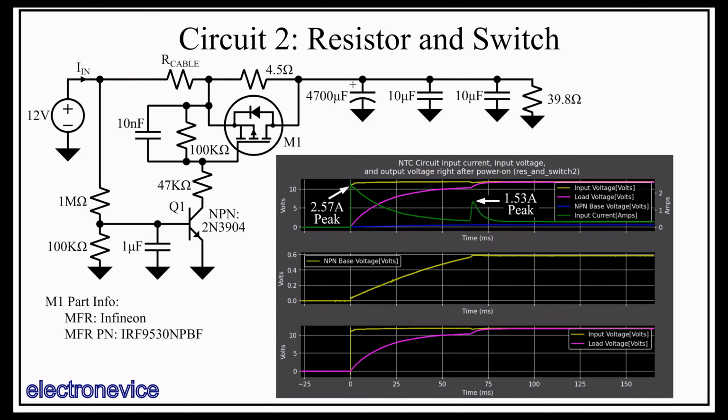However, since thermistor heat-up timescales are on the order of seconds to tens of seconds, you might need a different timing circuit than the one used here, as using this type of timing circuit would require a massive base capacitor to get a 10-second delay before the base turn-on, even with a 10 megaohm resistor. Those caveats aside, though, this circuit does limit the initial surge, and once the switch is closed, the input voltage is the same as the output voltage, minus a small drop from the switch resistance. This means the downstream circuitry can draw significant currents and have very little voltage droop on the load voltage.